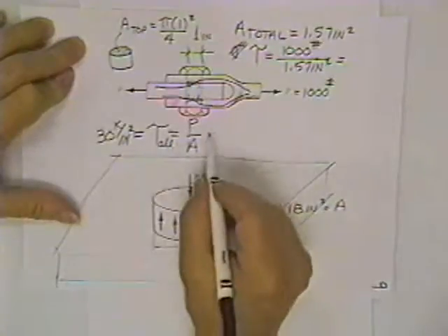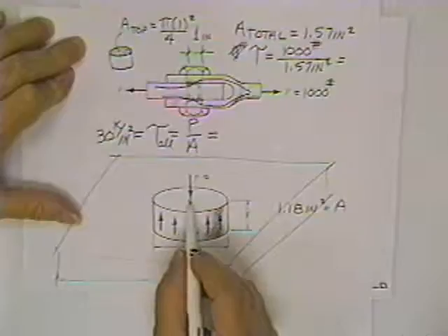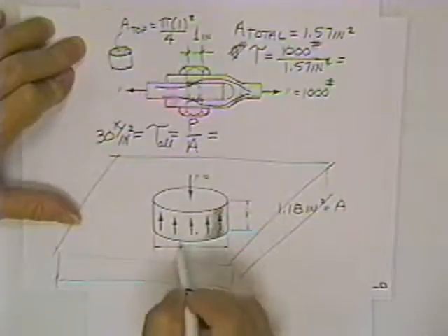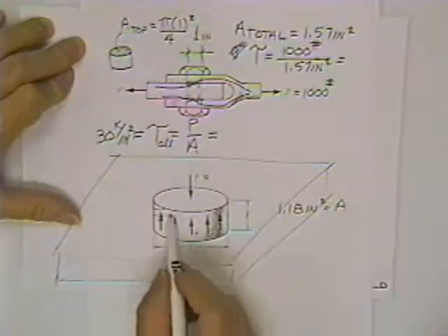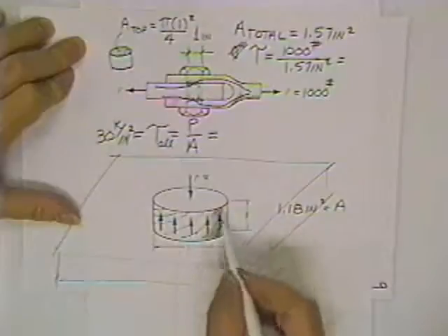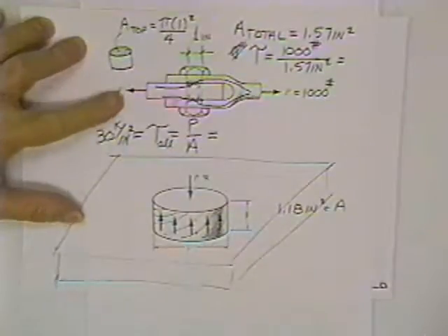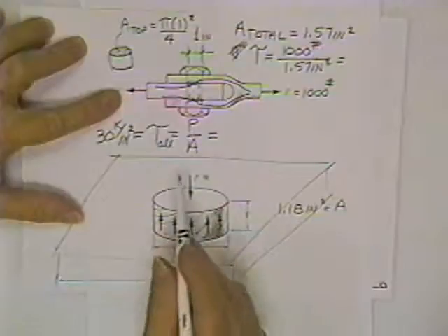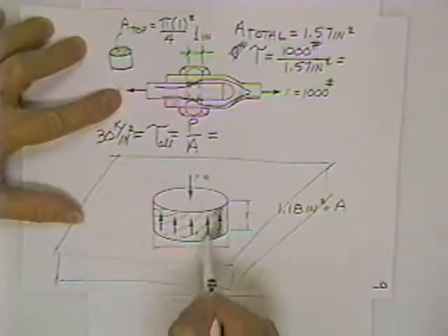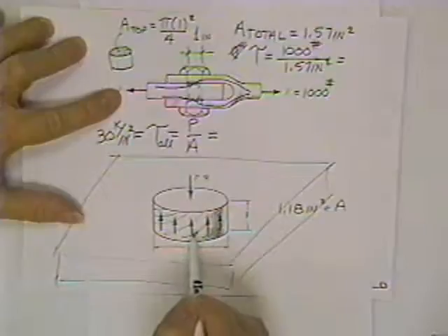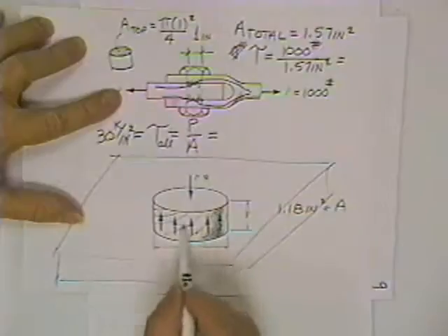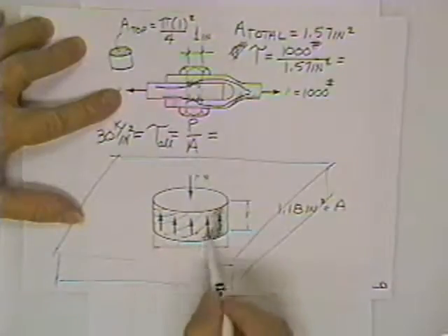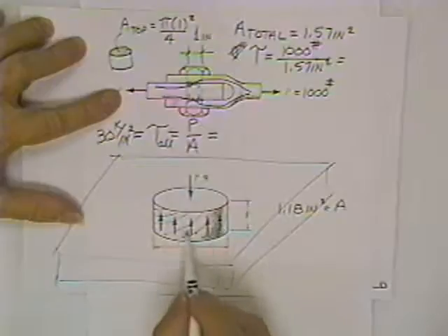The stress is load over area. I was asked how much load it took to punch this hole in the plate. So all I really need now is the area. Well, this is the area right here. Again, you find the area the same way as you did up here. If you take a punch, poke this thing out, let it drop on the floor, and pick it up, it'll look a little bit like a dime. The top's probably all rusty, the bottom's probably all rusty, but I guarantee you this surface around this tin can part is going to be nice and shiny because it used to be holding up the load, and now it has failed.